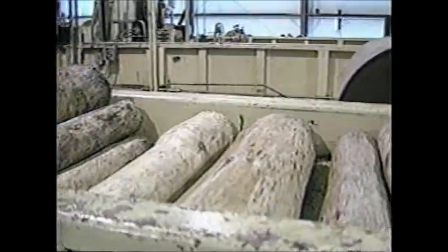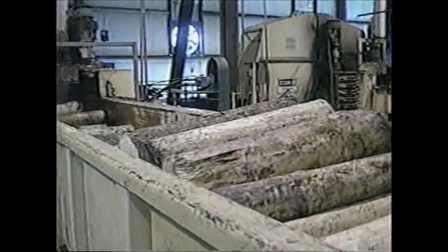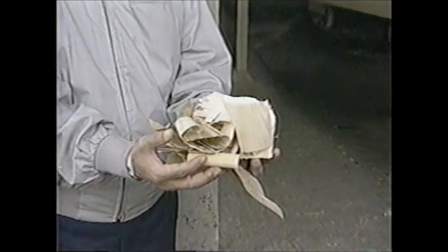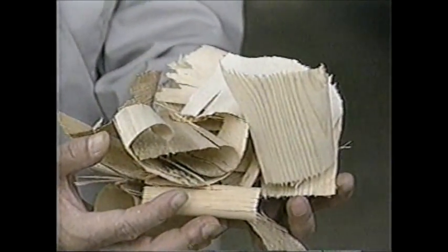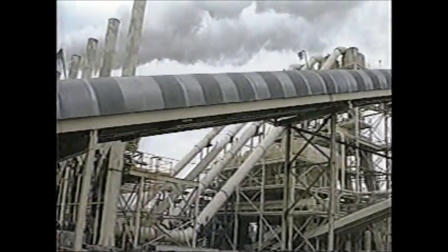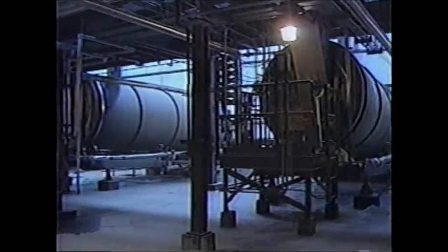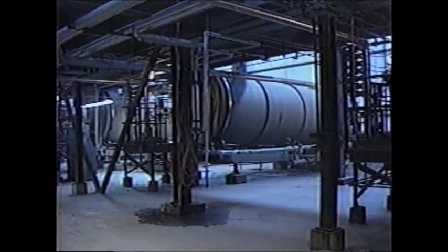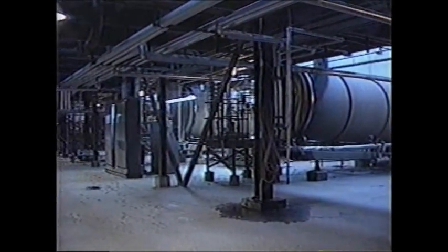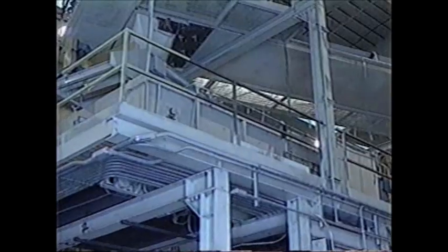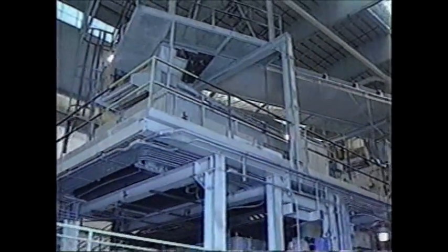The strands are chipped from the bolts, so the wood grain tends to run parallel to the long dimension of the strand. Here are a handful of strands resulting from the processing of a bolt. After chipping, the strands are then conveyed to a rotary dryer. After drying, the strands are conveyed to rotary tumblers and mixed with injected phenolic resin and a wax binder. After mixing, the material is conveyed to forming machines.